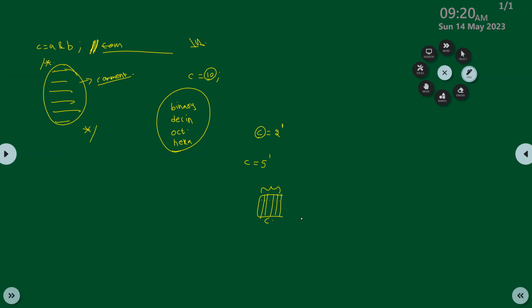And whatever value you are giving is up to you, and you need to specify which format you are giving. Let's say you are writing the number 8. You need to say which format you are writing, whether decimal, binary, hexadecimal, or octal, before that number. Let's say C is equal to 5 tick B 00110. Got it? This 5 tick represents that 5 bits of memory are allocated to the variable C. This B represents that you are writing the next number in binary format.